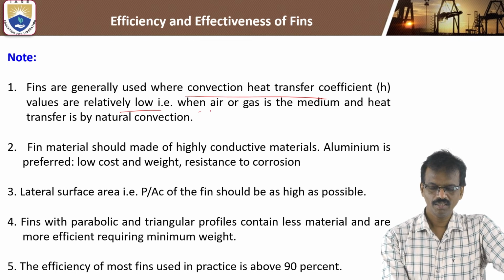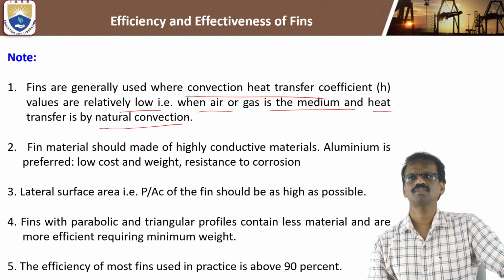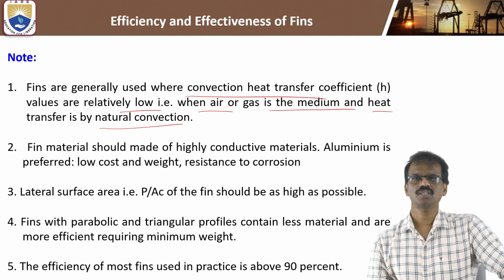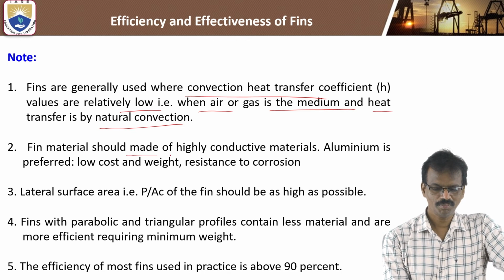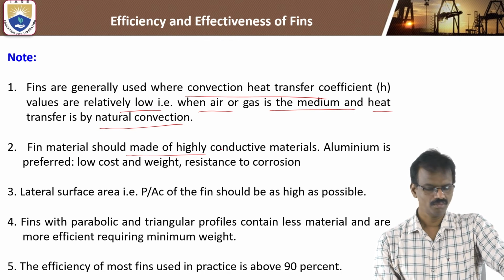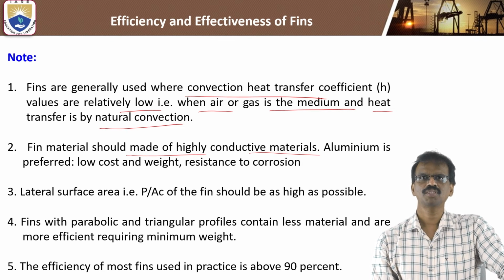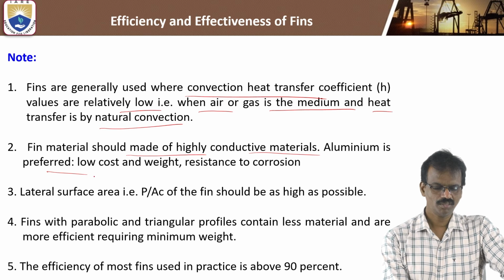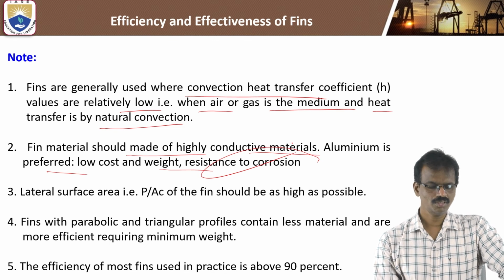When air or gas is the medium, heat transfer by convection takes place, from solid to fluid. Fin material should be made of highly conductive materials. Aluminum is the preferred material, with low cost, light weight and resistance to corrosion. That is a good material.